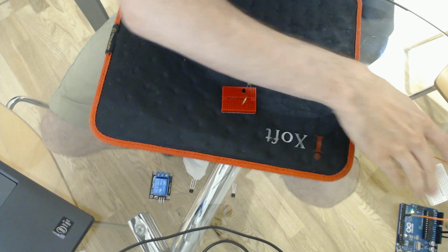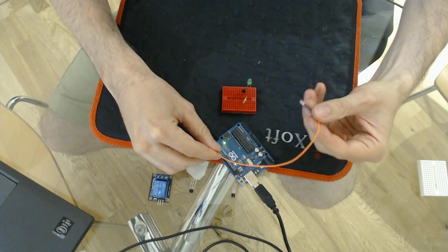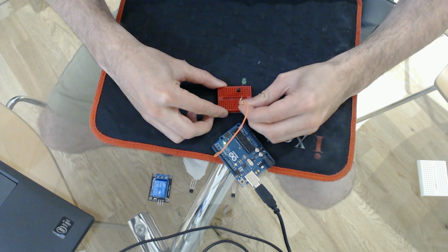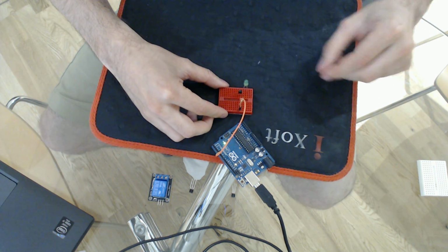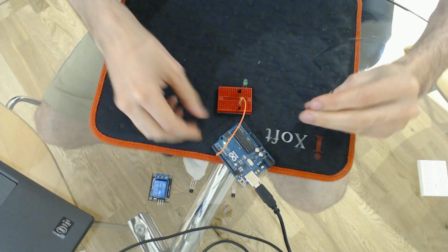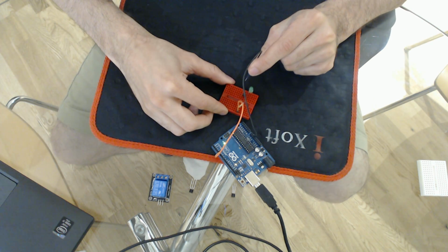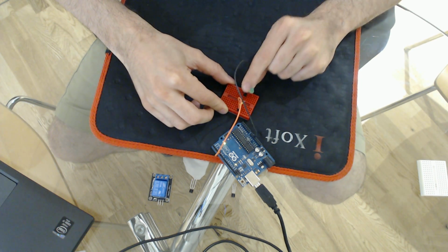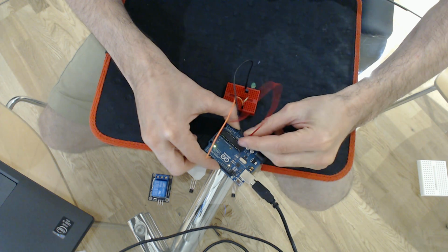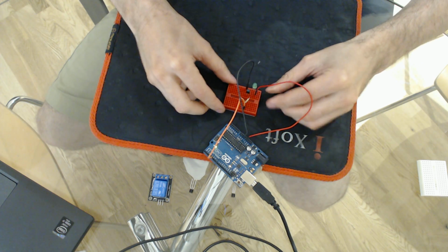And here we have the Arduino, which already has the cable connected to the pin 5, and we're going to connect the other end to the resistor. Right, here we're going to have our ground, and we connect to the pin ground, and then to the emitter, which is the third one. And last, it's our power. We're going to connect to the 3.3 volts, and then to the positive pin here.